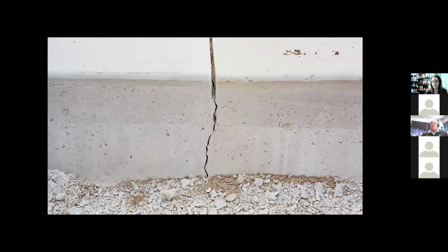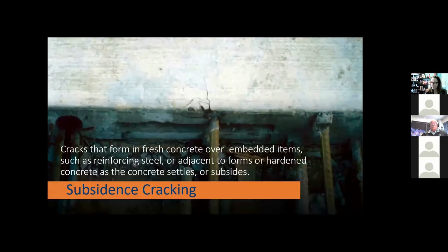Yes, there are cracks in my driveway. The majority, 99% of them, are in the joints as designed, and I do have steel in my driveway. But what's important there is that I have the stoop that I know is restraining an edge, and I knew I was going to get a crack propagating from the corner of a stoop where I did have isolation, but it was so much weight and restraint that it cracked, but I had steel right up against it within a couple inches. So the crack is tight and it's held together by the reinforcing steel. Steel doesn't stop concrete from cracking, it holds it tightly together. So it's up to us as to what is suitable for our design and what we can handle in construction.